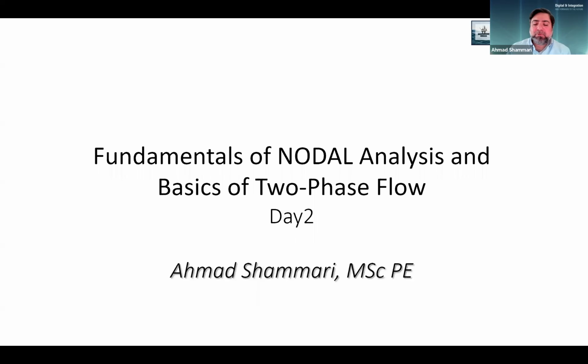Today, we will be focusing mainly on the inflow and how we calculate the IPR curve, or how we generate the IPR curve by selecting a few of the famous IPR methods. Of course, if you search the literature today, you'll find a lot more and different IPR methods that are developed for certain completions.